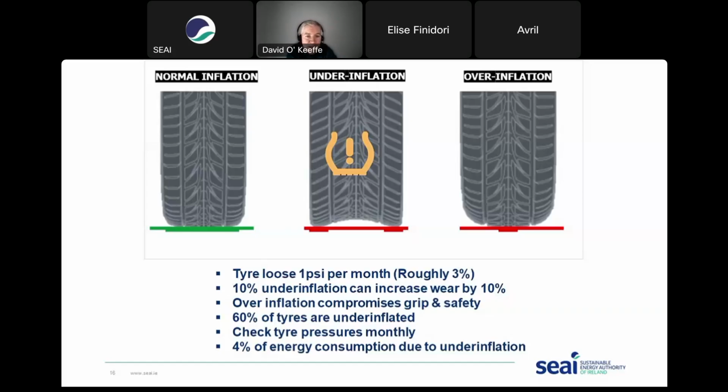So really, if you want to extend the life of that tire and improve performance and efficiency, you'd want to be checking it every 4 to 6 weeks. And what we have found from research is approximately 60% of people's tires are underinflated.